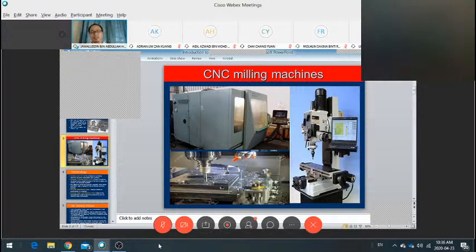In this case, what happens is that this tool holder, we call this the turret, or spindle. Okay, sorry, this is the spindle. This spindle will not move left and right, but it will just rotate, and that will cause the tool to rotate as well. So how does it cut from left to right? What is moving here is the table. The table will move to the left or to the right, and as it does that, this cutting tool will cut through. That's how you do the cutting.